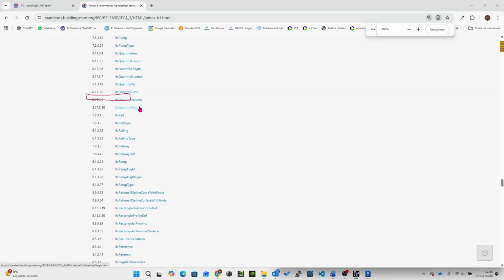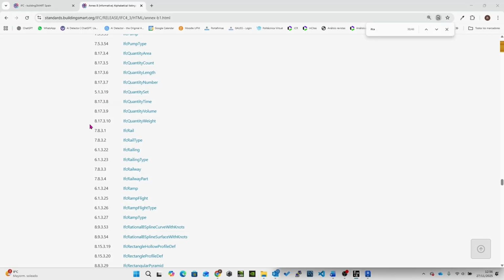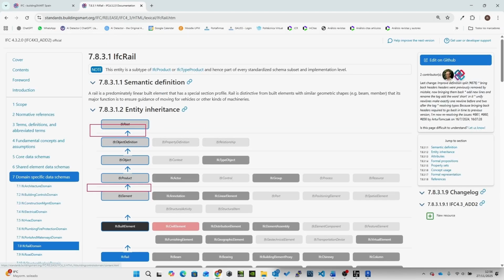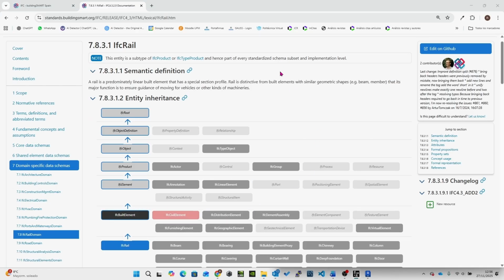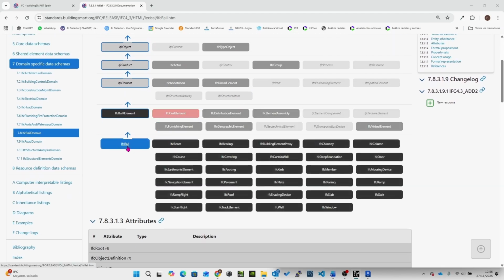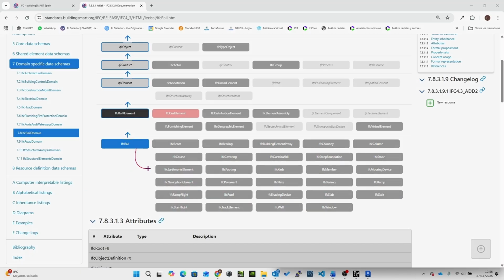I will zoom in here. We can see that I have entities related to rail, I have entities related to ramps, so I have entities related not only to building. If I click on rail, I will see that there are a lot of links between different elements of the model, and inside rail, for instance, I can have different entities, different parameters, or let's define them as families or types, that are inside this category, and these families and types I don't have in a Revit environment.